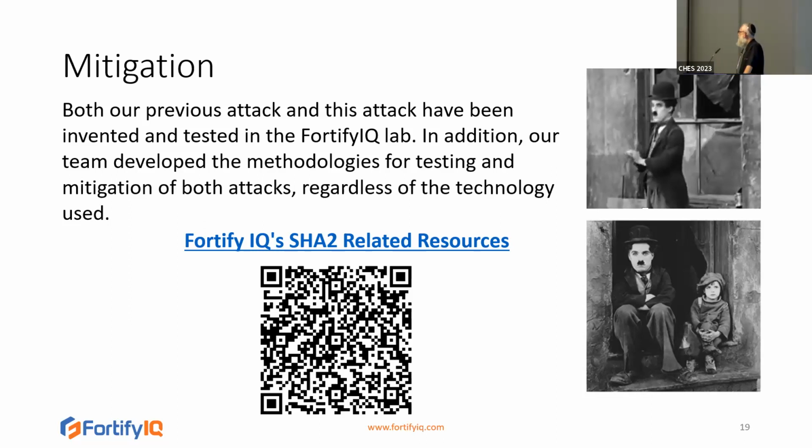Hi, you didn't specify what kind of adder you were using and if they influence the side channel leakage. You mean how we implemented the adder in the FPGA? Yeah, because there are several kinds of adders that you can implement for a 32-bit addition. Did you check the influence of that? I cannot exactly answer your question now. I believe in our Verilog we just used the built-in addition. In any case, what we have is a proof of concept that at least for one implementation of addition in hardware, probably the default one, our attack works. Thank you.